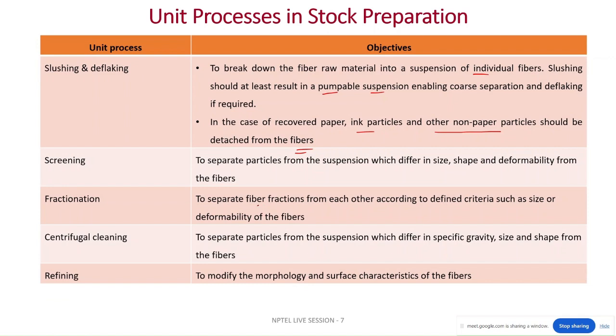Fractionation is to separate the fiber fractions from each other according to defined criteria such as size or deformability of the fibers. Centrifugal cleaning is also used to separate the particles from the suspension which differ in specific gravity, size, and shape from the fiber.